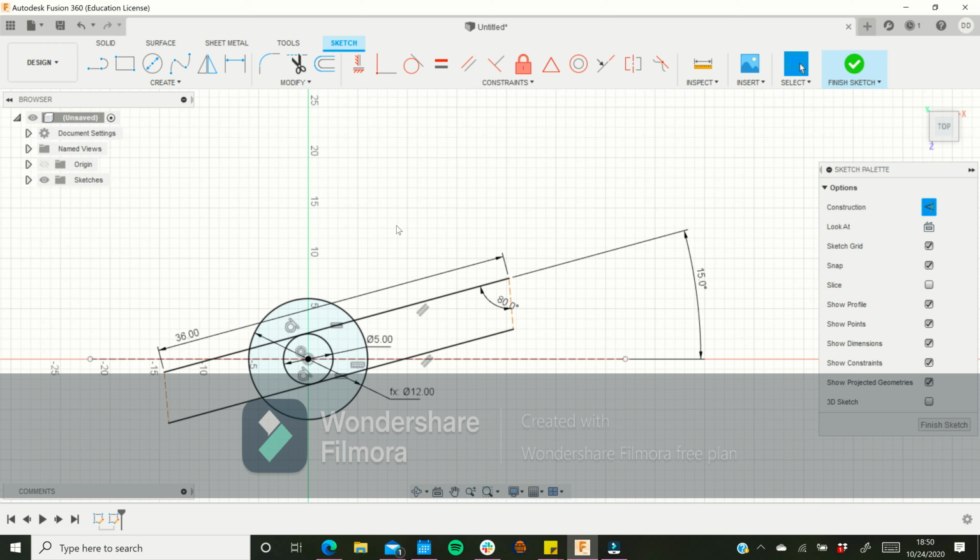One thing I haven't mentioned, a good way to tell if something isn't completely constrained the way that you want it to is to click on it and move it around. And if it still moves in any direction, that direction can help you figure out how it's not constrained. So for this, I can dimension one of these points from the origin, and I want it to be 18 inches away from the origin, and now everything is constrained. It won't move. You can tell because these construction lines are blacked out and they're not orange anymore. So yeah, that's how everything's constrained.